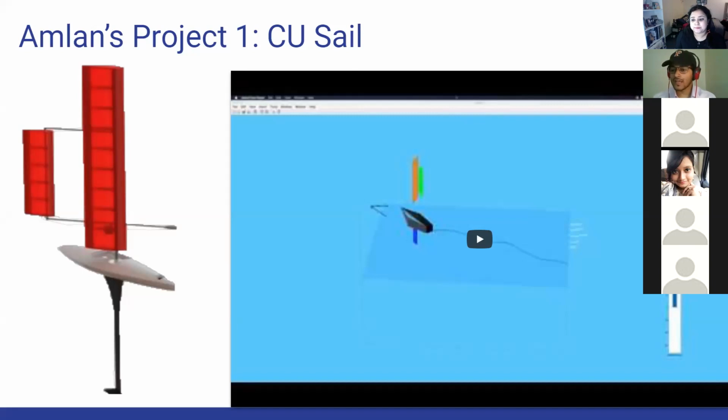Okay. Why are there two sails? The two sails, one of them is for propelling purposes. So that provides thrust. The one in front that you see gives you the force that you need to move forward. And the one at the back is for orientation. The rudder that I was talking about, which stays under the water, has been replaced by the external rear sail.